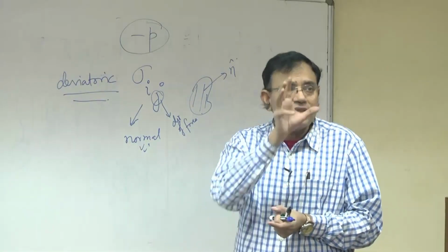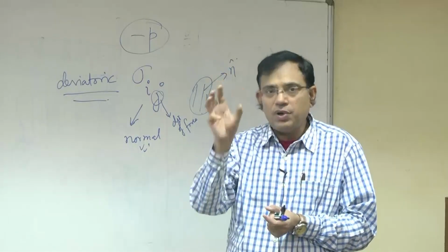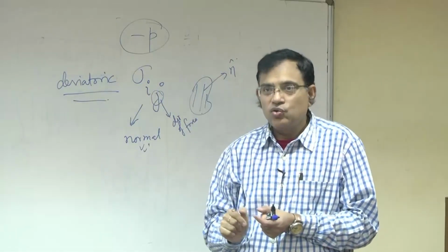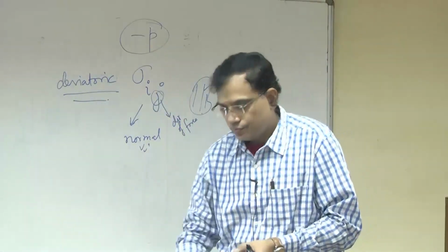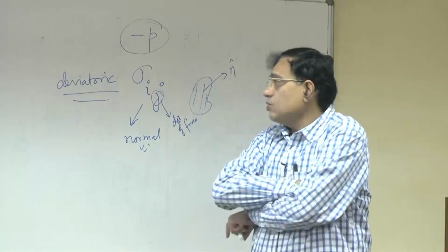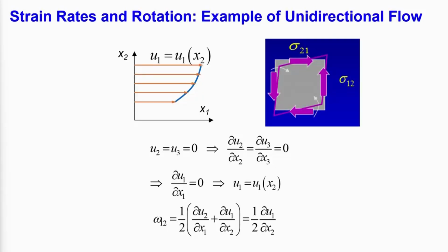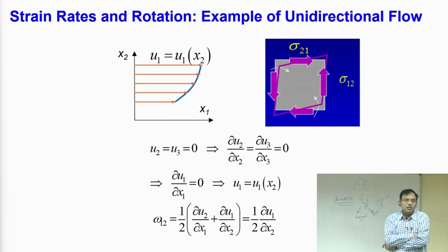So, the whole idea that I want to convey to you, that be it mass, be it momentum or be it anything else, we are able to write it in a form where you have the mathematical structure very similar. Now, just because fluid flow has stress due to the deformation, to calculate the deformation, what you require is the gradients of velocity components. So, if you have a velocity component, its different derivatives will give you different aspects of deformation.